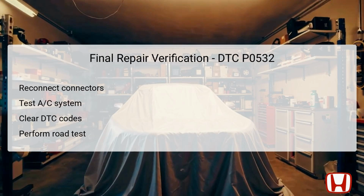After completing all necessary repairs based on diagnostic findings from steps 1 through 5, the final repair verification process ensures that the AC system operates as intended. Start by reconnecting all previously disconnected connectors, ensuring that everything is securely fitted to prevent future issues. Following this, test the AC system to verify that it cools correctly, checking for any unusual noises, performance drops, or error codes.